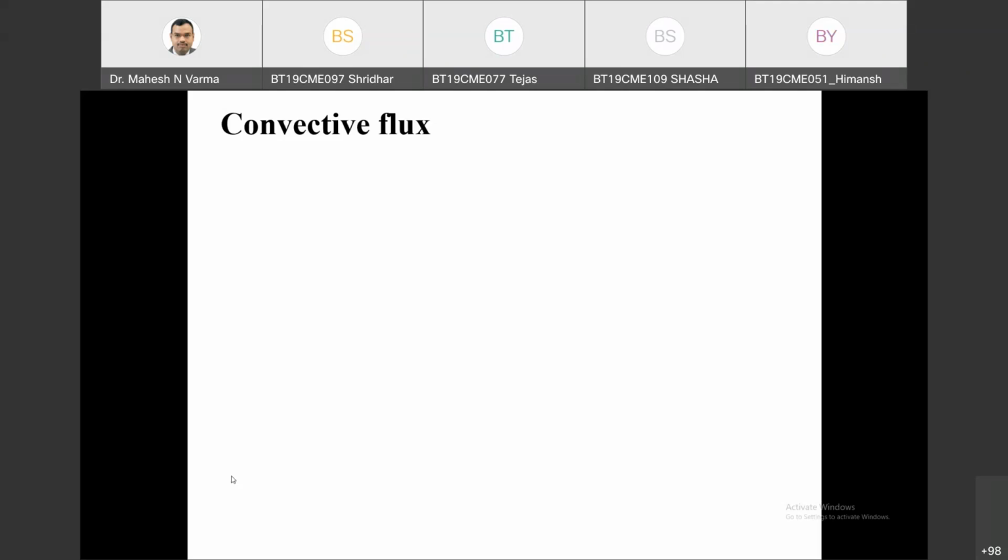And where is bulk motion coming in H into delta T? So the driving force is temperature, but in the heat transfer coefficient carries the characteristics. Yeah. So the overall heat transfer coefficient is a function of velocity. Yes, sir. Is it so? Yes, sir. How? Do you remember any relation between H and velocity?